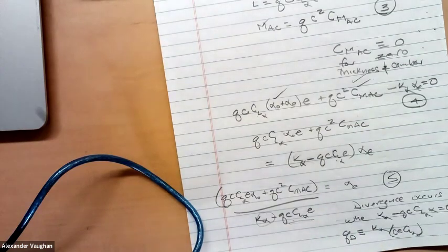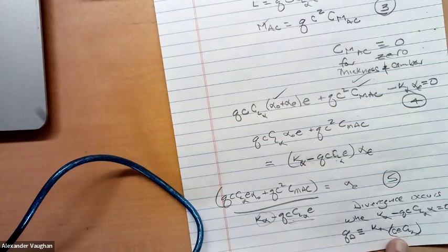Okay. Note what happens if E is negative. That is, the aerodynamic center is behind the elastic axis. Then the corresponding Q is negative, but that's not physically possible. Or if you prefer, think what happens when E is 0. When the aerodynamic center and the elastic axis coincide, then Q goes to infinity. The divergence Q goes to infinity.